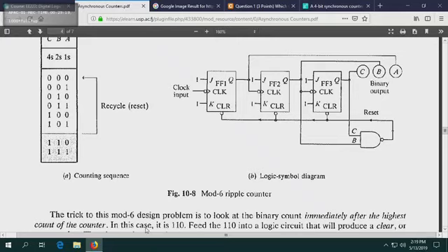If you want, you can use a sum of product system or product of sums, but that uses a lot of gates. If you just use one simple NAND gate, you can then activate the clear line by sending an active low. Okay, you get what I'm saying now? So the moment that particular combination is reached, the combination of having 1, 1, 0. Flip-flop 3 and flip-flop 2 will have 1s. Flip-flop 1 will have 0.